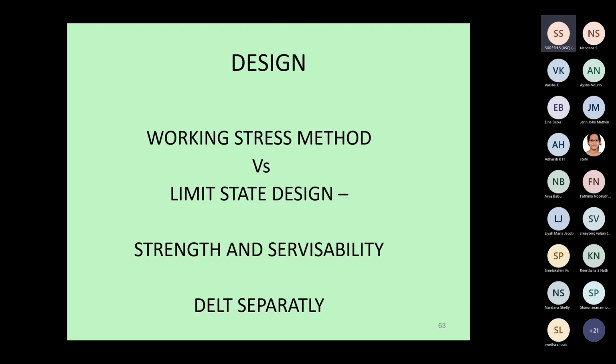Now, the limit state design, as a modified factor, is used in the ultimate load design used in Europe at that point of time. Now, every country has changed to Euro code and every country code has changed to limit state design. Even in the changeover path, after the working stress design, some of the countries used an ultimate load design, which was a combination of working stress and a limit state design.